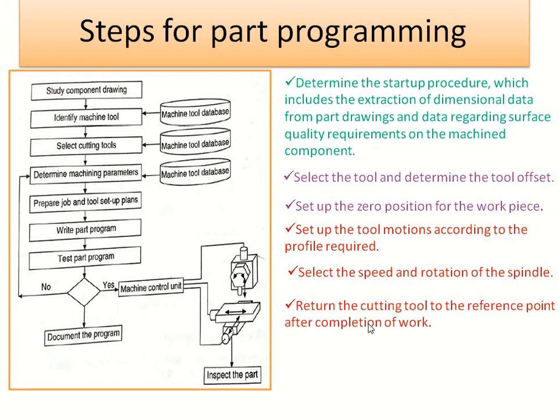Then return the cutting tool to the reference point after completion of work. And finally, end the program by stopping the spindle and the coolant. These are the steps we can follow to complete the program.